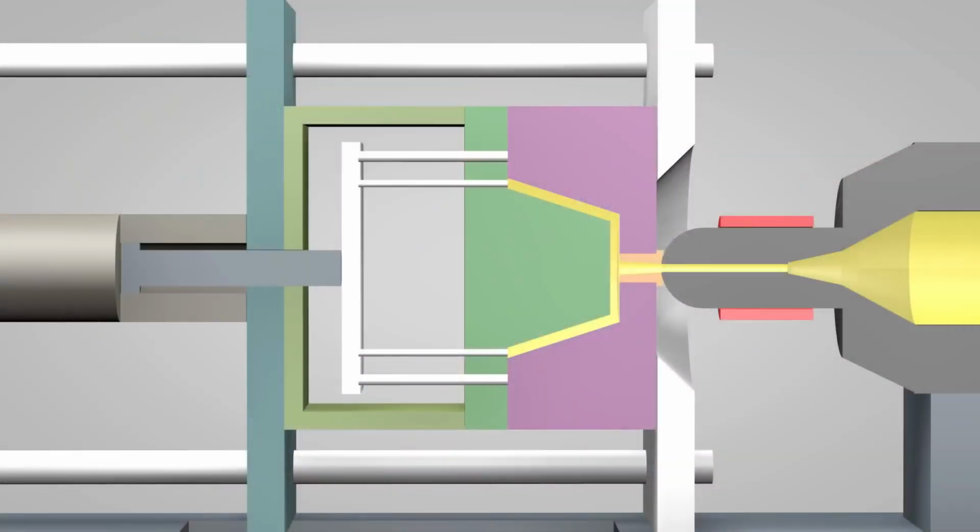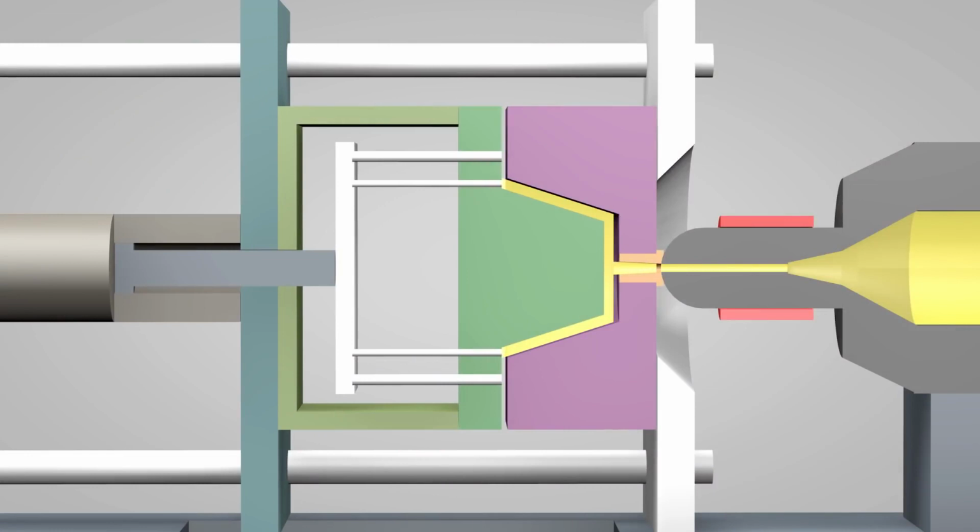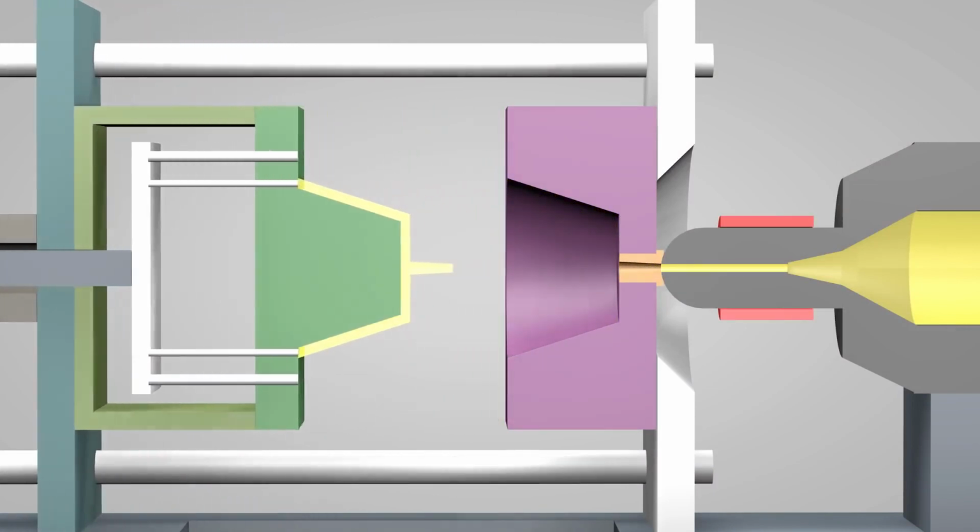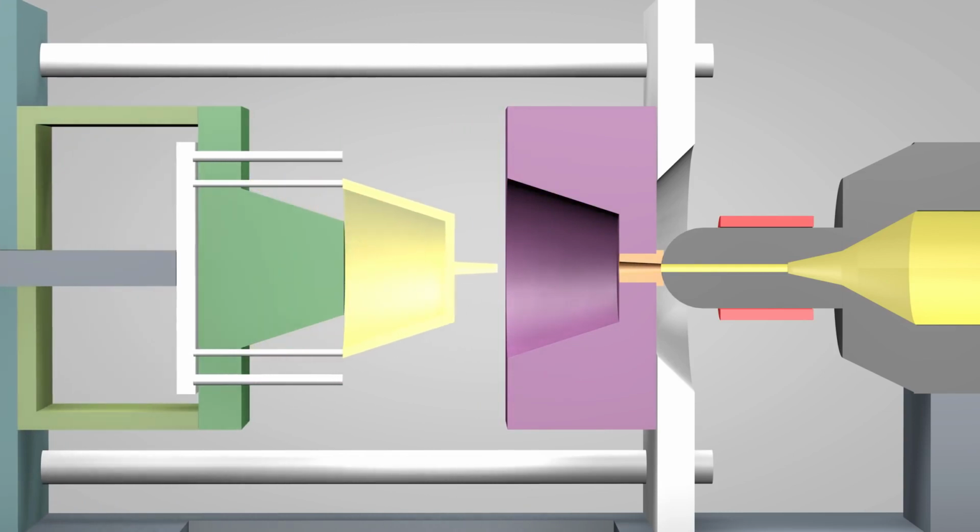As the mold opens, the volume increases without introducing air, which creates tremendous suction that holds the mold together. So at first, the mold slowly opens several millimeters to allow air to rush in and break the vacuum, and then the mold quickly opens the rest of the way so the part can be removed. These precision machined steel molds can cost hundreds of thousands of dollars. Removing the part from the mold can be difficult.